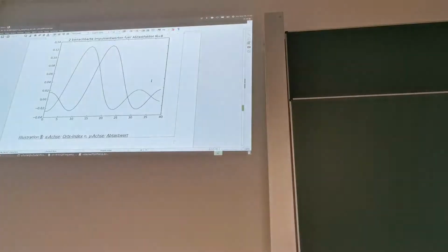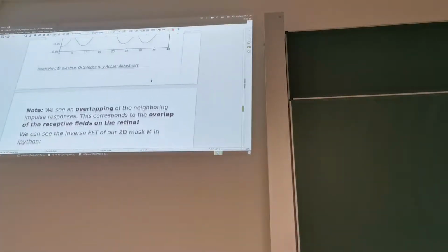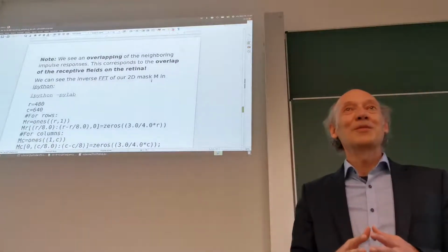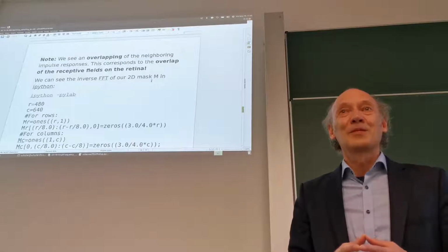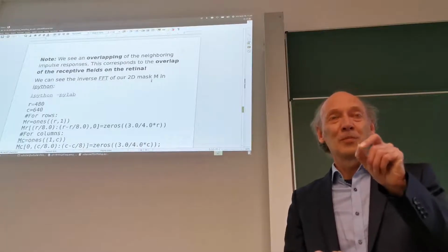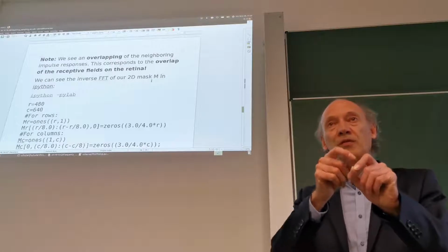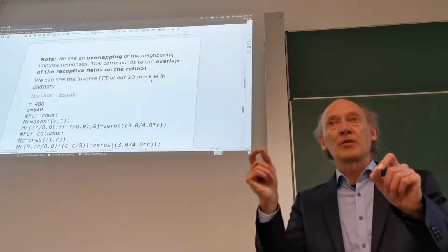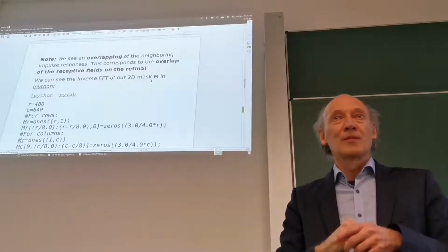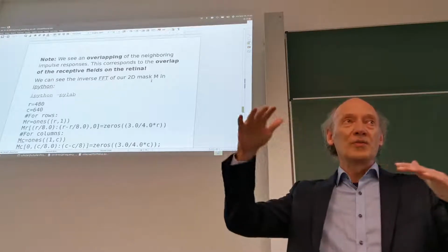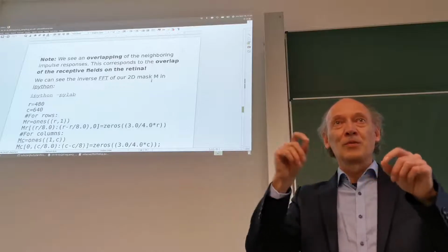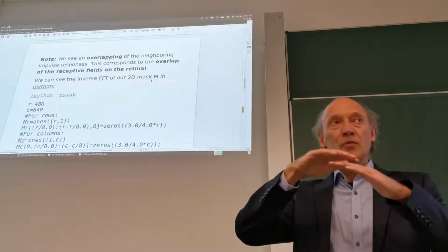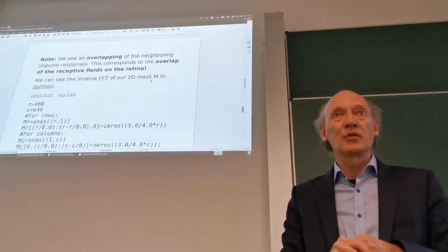Here in this case, the overlapping impulse responses. Does it make sense? So the same pixel of the input image goes to the result of several image pixels at the output image after low-pass filtering and downsampling. And this is actually important for the smoothing effect. We don't want the next pixel jumping a lot at the output, because we want to smooth it using this low-pass filtering process.